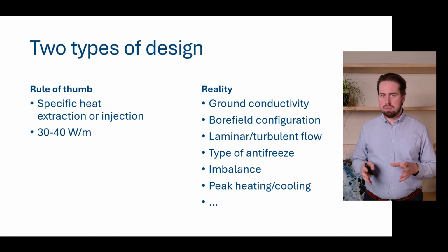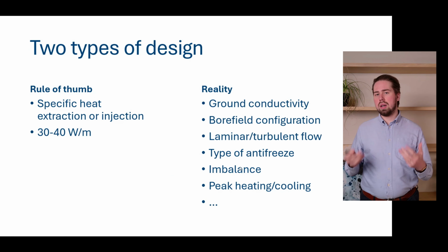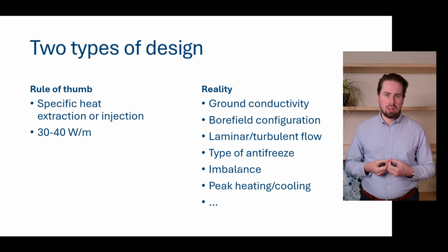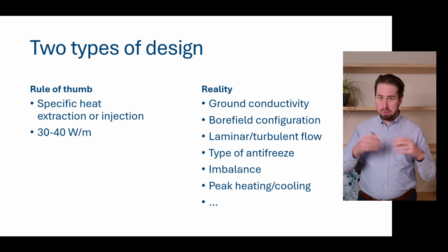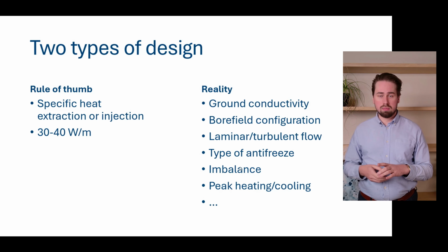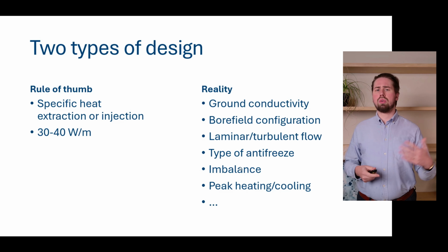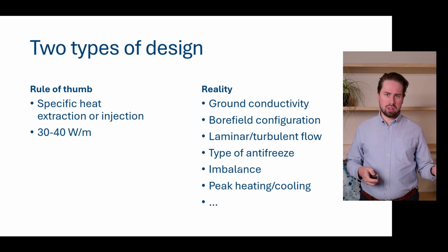Now, we can do that in two ways, basically. On the one hand, we have rule of thumb. Here we say, okay, we have a specific heat extraction and injection from experience, and we know that our borehole can deliver 30 to 40 watts per meter.